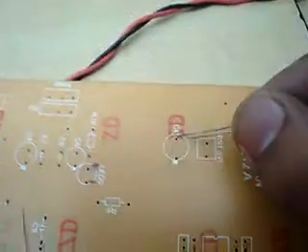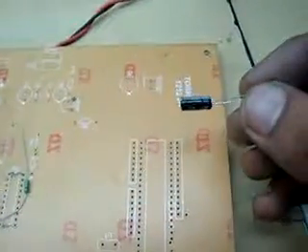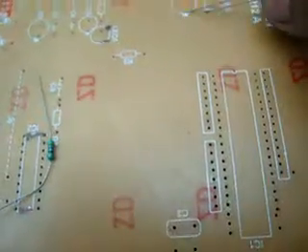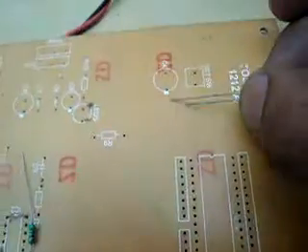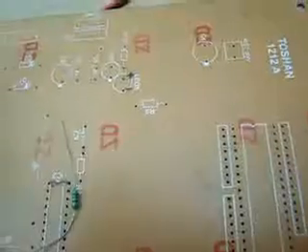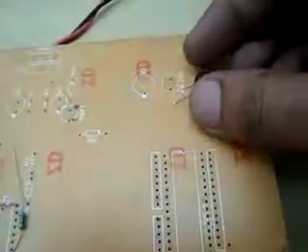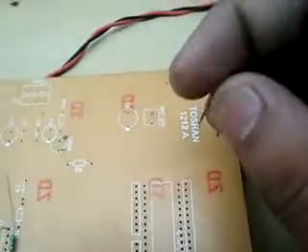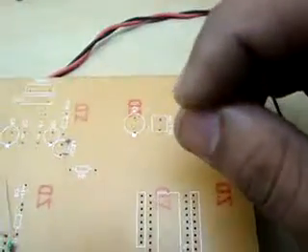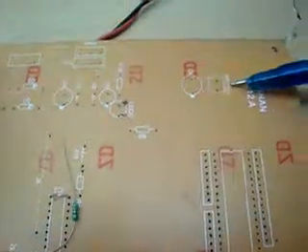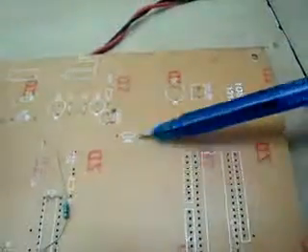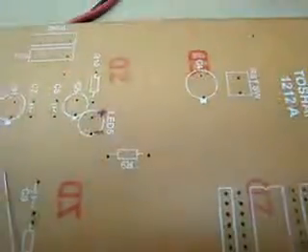This is your microcontroller circuit. Across C4 we use a capacitor of 10 microfarad, 15 volt. Positive is on the upper side and negative is on your lower side, on which a symbol is marked. On this side we attach a micro switch, push button, and this is the capacitor and reset switch, and on R9 we use a resistance of 10 kilo ohm.